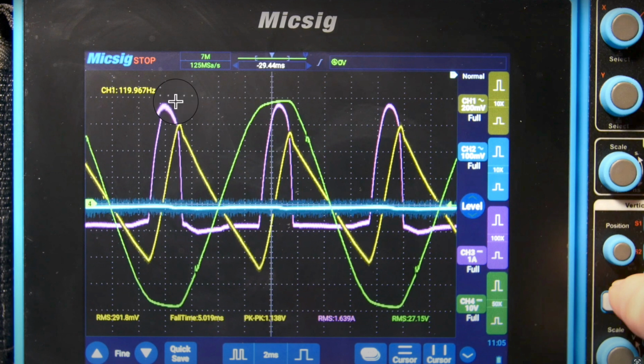So that's a little harder to say because this might have a little curve to it. It's kind of a little bit harder to read. So it might be better to use this. The formula is going to come out the same. Okay. The time frame between here and here is shorter. This time frame is longer. Okay. This is only 1 amp. So 1 amp times this time frame is going to be equal to whatever current this is times this time. It's going to be a current-seconds balance. Okay, so the current here and here, it's going to be close to that.